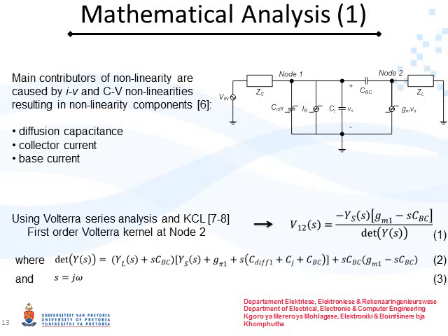In order to design the predistortion linearisation technique, a mathematical understanding of the nonlinear components and how they relate to the IM distortion components should be obtained. The dominant IV and CV nonlinearities found in the silicon-germanium HBT result in the following nonlinearity components. The collector current IC is a nonlinear function of the control voltage V pi and relates to a nonlinear transconductance. The base current IB is also a nonlinear function of the control voltage and therefore follows the nonlinear characteristics of the transconductance. The diffusion capacitance C_diff is directly proportional to IC and is therefore inherently nonlinear.